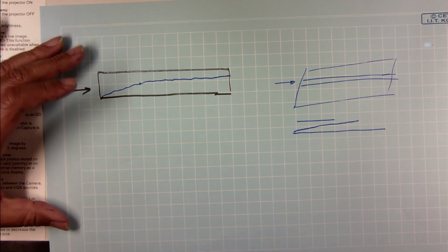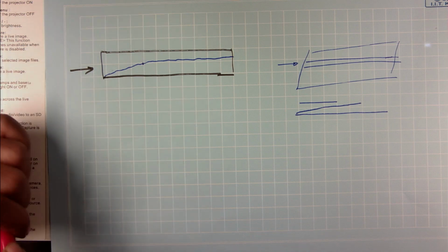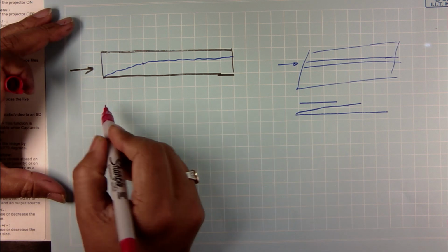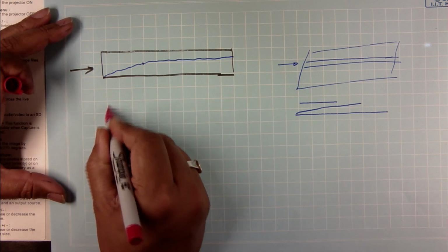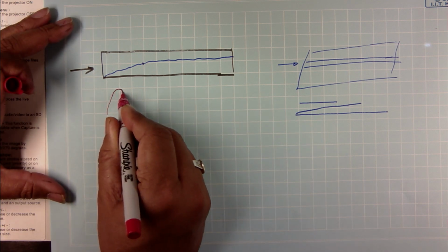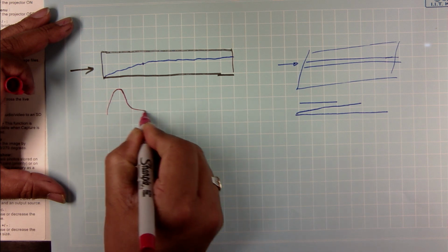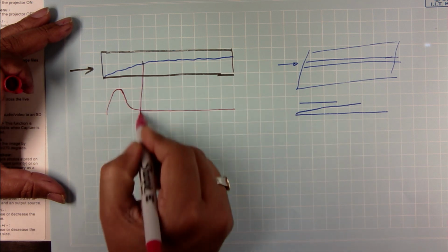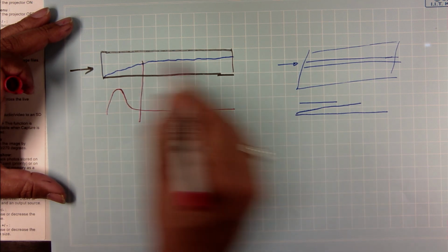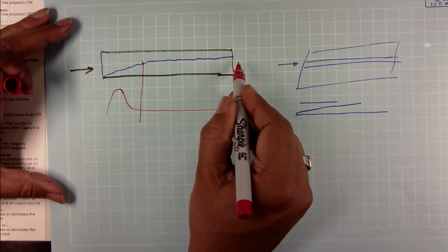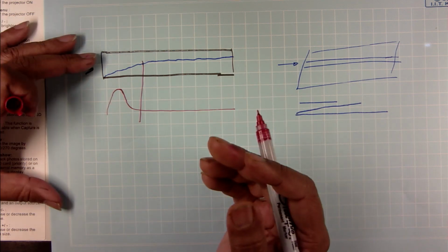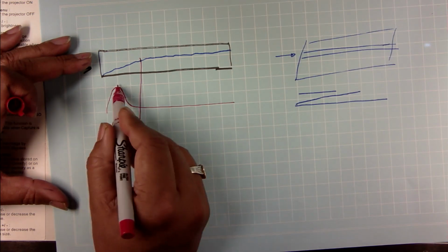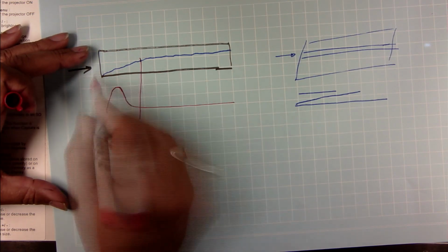And so if I plot the heat flux, or the heat transfer coefficient, in the direction of the flow, I am going to get a very high value of heat transfer, and it is going to rapidly go to 0, because at some point the resistance in the film is so high that you do not get as much heat transfer anymore. Okay. So the trick is to capture the heat transfer.